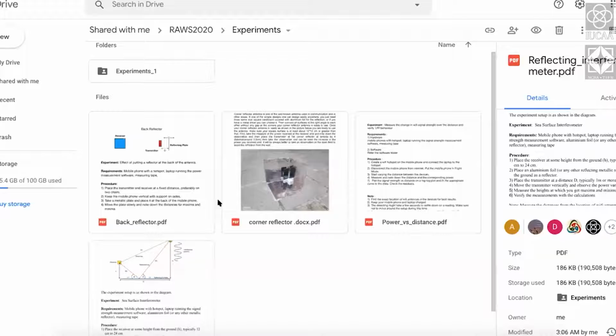Whenever you are in the measurement mode, try not to cause any disturbances by moving around the setup or by moving your hand. These devices are actually very sensitive. Their noise floors can go to minus 90 dBm, so any small movement might change your measurement. Try to avoid those kinds of things. It should not affect very much, but it will give you better results.